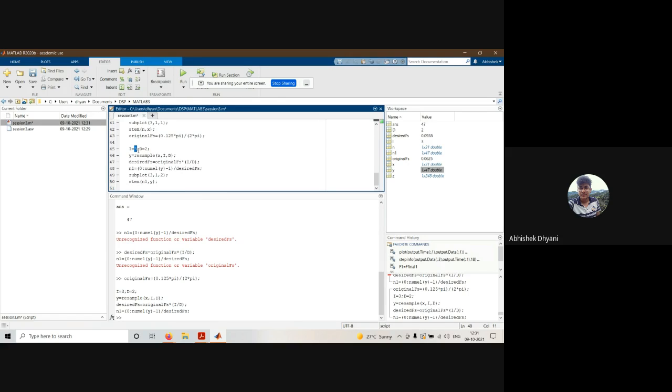So it means that there will be an overall interpolation, because the factor was I by d and I is greater than d, so the overall sequence will be interpolated as compared to the sequence x. Similarly we can do for I by d equal to 3 by 4. So I is 3 and d is 4. Now in this case, d is greater than I, so there will be an overall downsampling.